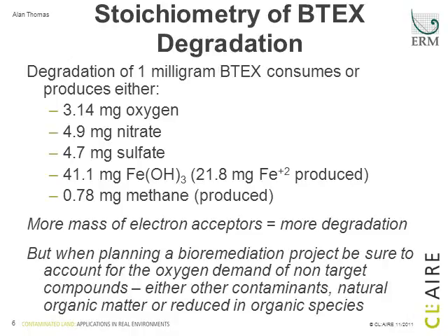Just emphasizing again the stoichiometry aspects. Again, you hopefully have read about this in some of the background reading. But effectively, through stoichiometry, we are able to work out a mass balance of the quantities of reactants and products, and so we can really engineer the amount of substrate or electron acceptor that we add to the subsurface to stimulate and effectively degrade the mass of target compound that's present. The more mass of electron acceptors that we can add, typically the more degradation that is possible.